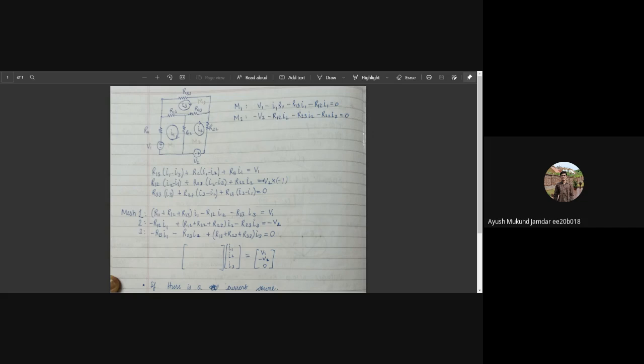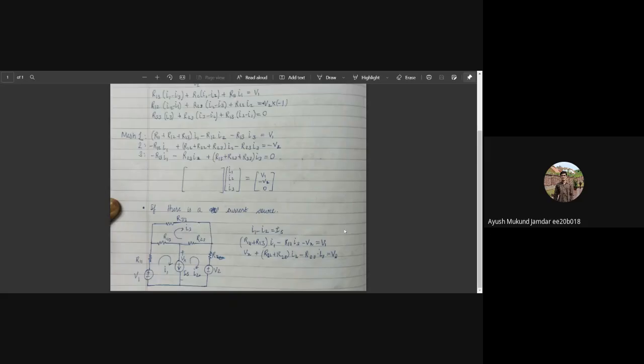Again, one can ask what if there are current sources as well. When there are current sources, we can use the same approach we used for voltage sources appearing in the nodal analysis. That is, we can assume an arbitrary unknown variable, let's say Vx, the potential difference across the current source, and we'll have one more equation to solve the circuit, as you can see in the example given over here.